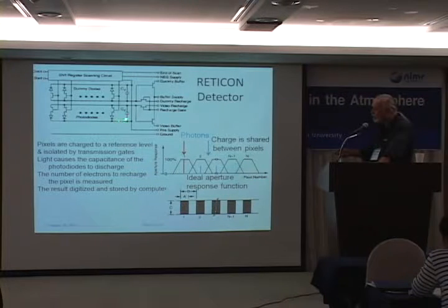And the electron-hole pairs created by the arriving photons or thermal generation will gradually discharge the junction. And then when you recharge the diode, you measure how many electrons it takes to put back on. Each photodiode can store up to 62 million electrons, and your electronics has to be sensitive enough to recharge that.